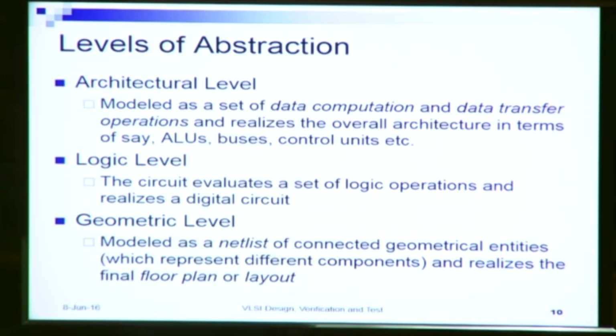Then we come to the logic level. At the logic level, the circuit is represented basically as a set of logic operations, or let us say a state machine with respect to a controller and a set of Boolean equations that represent the register transfers that happen. These Boolean equations and state machines together will form the behavioral description at the logic level. And what will we do in the logic level? We will realize the circuit in terms of a digital circuit, in terms of gates and flip-flops.